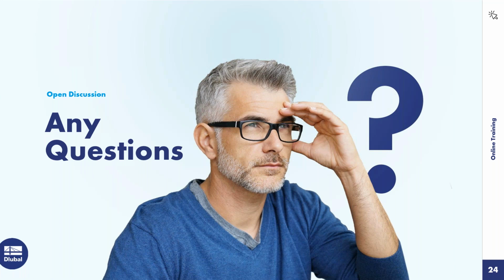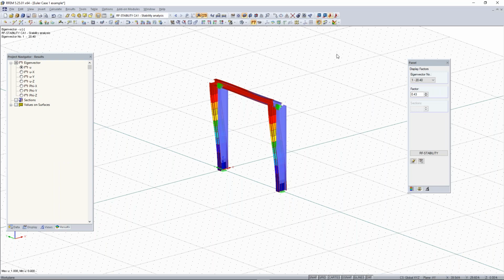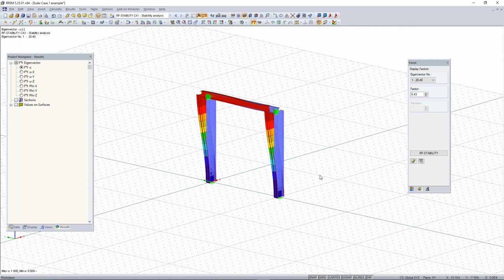Yeah, so we do have a direct integration method with AutoCAD. If I go back to RFEM, you can import models in from AutoCAD, and things like center lines are imported as a .dxf file. If you're integrating line elements like center lines, then that works great. You can save the cross-section name and material to those lines in the layers in AutoCAD and have those come over as members.